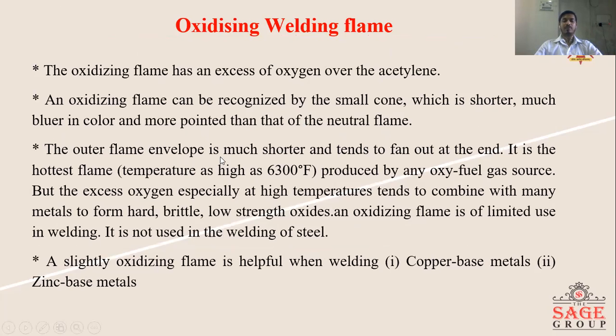The outer flame envelope is much shorter and tends to fan out at the end. It is the hottest flame, at a temperature of about 6300 Fahrenheit, produced by any oxy-fuel gas source.